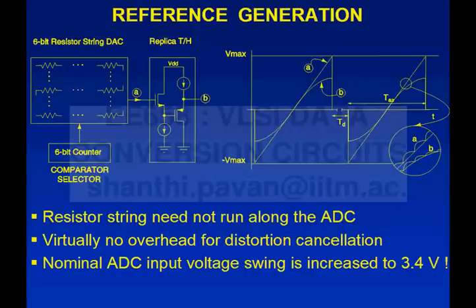But please note that first, it doesn't have to swing rail to rail, correct? Because at every step it's only jumping up by 1 LSB, okay? So the amount of current that this needs is very, very small, and the AUTOZERO phase itself is very long. In our implementation, the time for AUTOZERO is actually 4 clock cycles. So in principle, this doesn't have to have any current at all, okay? First of all, its output swing changes by 1 LSB every 4 cycles.